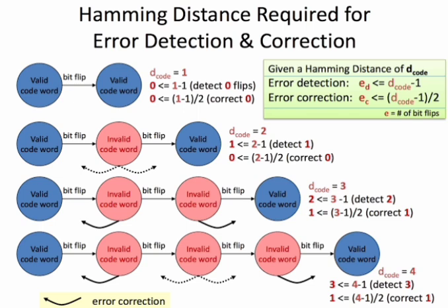Frequency distortion. This type of distortion exists when signal components of different frequencies are amplified differently. It is caused by stray capacitances and stray circuit capacitances. Phase distortion. It results from unequal delays of the signal of different frequencies. Note: capacitors and inductors cause frequency and phase distortion, but not amplitude distortion, as they are linear elements.